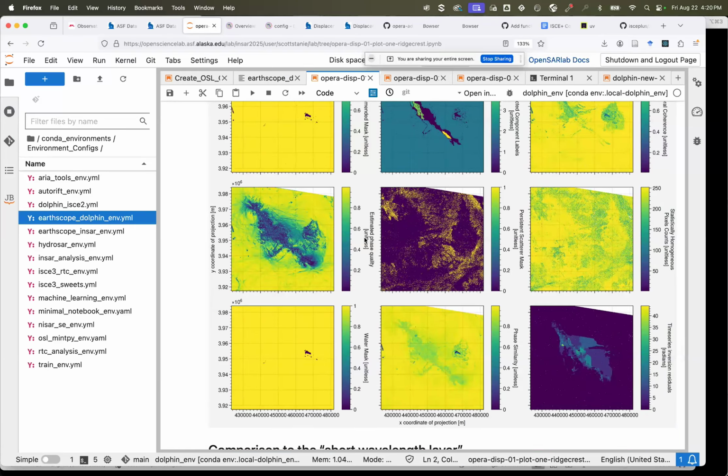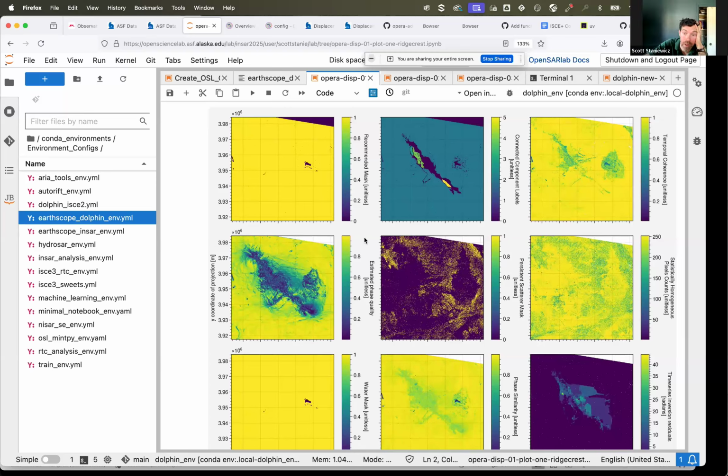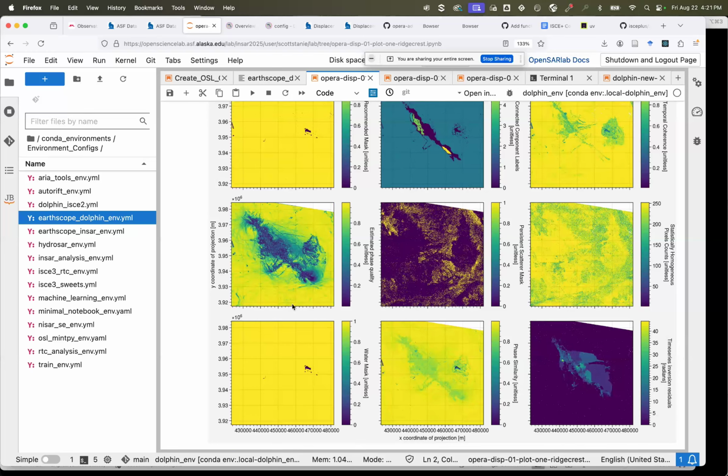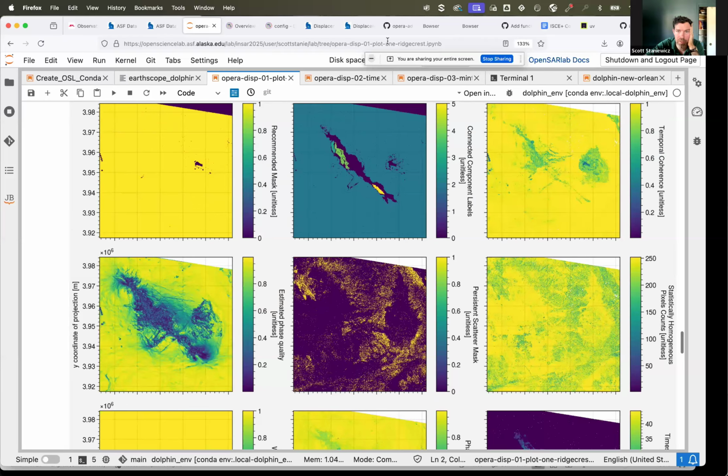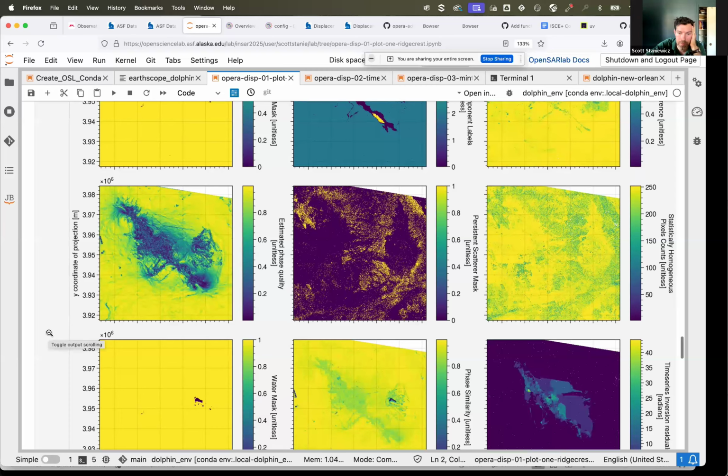That sounds like a really useful thing for people using HyP3. Yes, exactly. The person who asked said that in GAMMA, we don't get this. How can we use it for MintPy? You can take snaphu-py and run it on your unwrapped phase and get connected component labels for pretty cheap. That's great. Actually, we should talk to the ASF team to integrate that as a feature, for folks that click on the ASF prepare for MintPy option, and it could just run this additional script. Yes, if you can't find it in there, I'll send it. It's in the dolphin repo, like the actual production code.